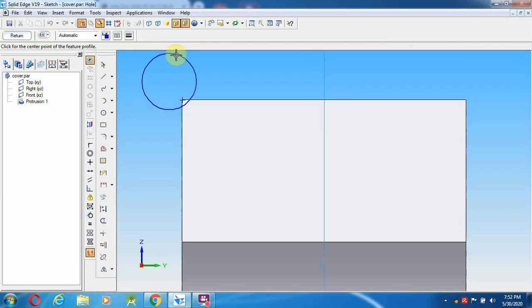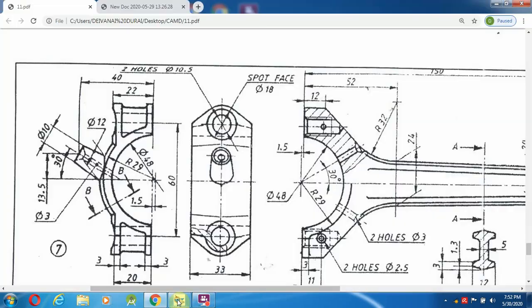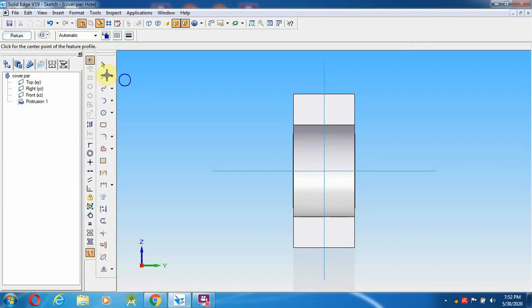Select the particular surface, give fit as well as go over here. So the distance from mid to what is the height, so of 60 mm. So from middle to 30 mm. So go over here, select a line from mid. So actually this is the mid.